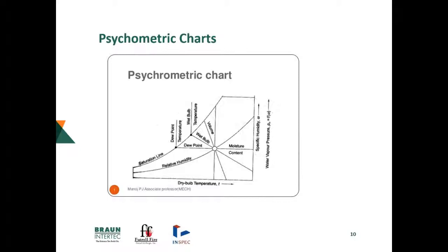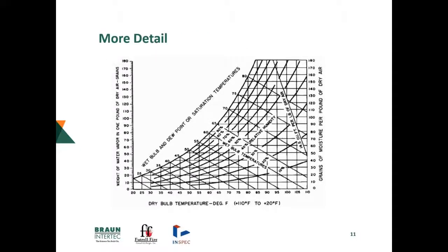It's that simple. So here is one of those things. If you look at, call it 80 degrees inside, run up to the 50% relative humidity line, and out to the left, you're going to be in the 50-degree range, roughly, for relative humidity when you're going to have dew point occurring.